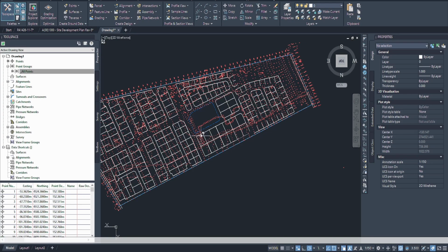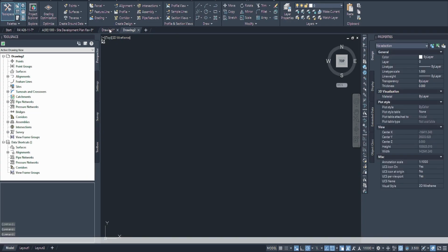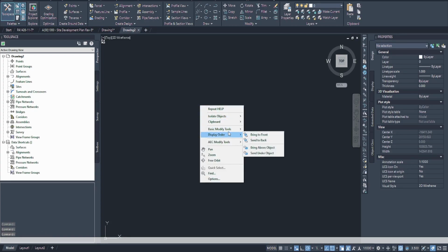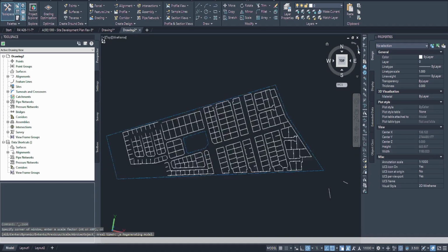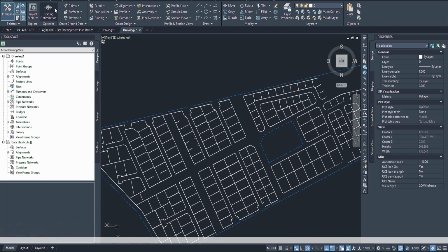The next step is to use the text file, but for that I'll create a new drawing and start from the bottom again. I'll just leave this one so that I can copy the STP from here. So I'll just start again by opening a new drawing, and I'll select the STP data, select similar, and I'll copy, and this time I can just paste the original coordinates because it's already moved to the right position and orientated. Well, I'll just have to turn this one around as well. All right, perfect. Now we can import the points.